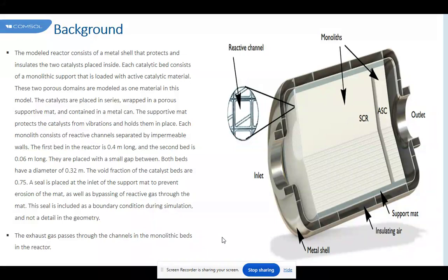In the core region, the reaction rate starts high, then it progressively decreases until full depletion of CO. It can be seen from the equation that the denominator in the rate expression is close to 1, and also that, given the inlet composition, YO is almost constant. Hence, the main factors driving the reaction rate are temperature and YCO. According to this simulation, the former is comparable in the four cases, so the latter dominated the reaction rate among all of the other parameters in the rate expression.